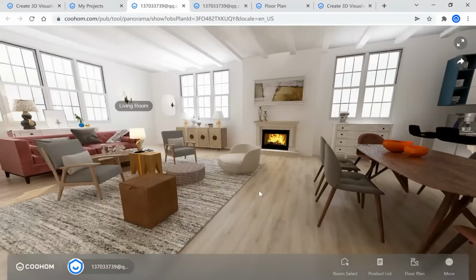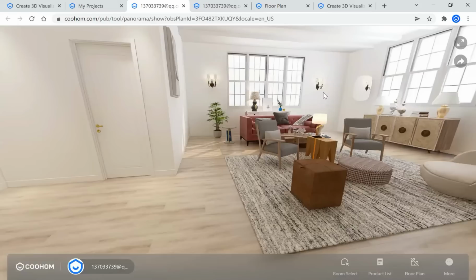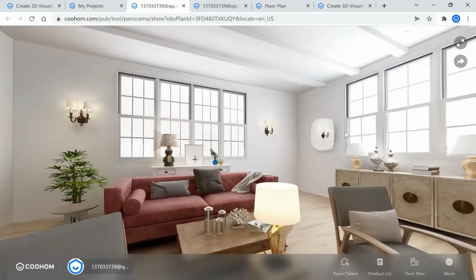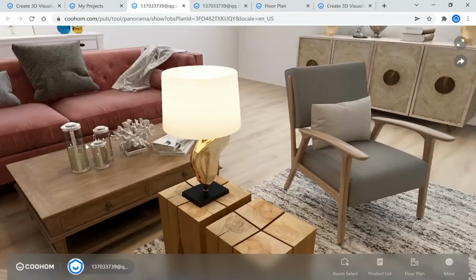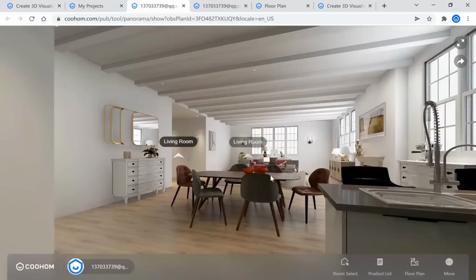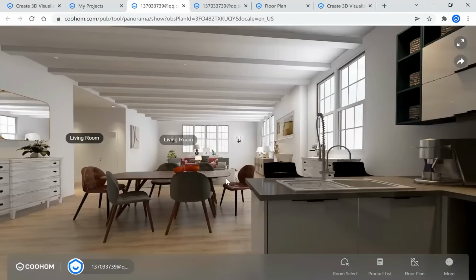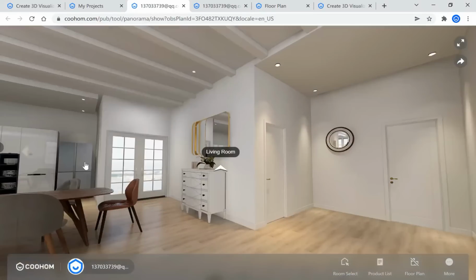See here, yes, this is the panorama I made before. And when you go to the living room, click the button, then you go to another standing point and you can see exactly what's happening here or there. And this one could be kitchen. So when you generate your panorama, you can rename it, like as kitchen, so that it is shown on your walkthrough tool as text, like living room or entry, and here you can rename this one as kitchen.